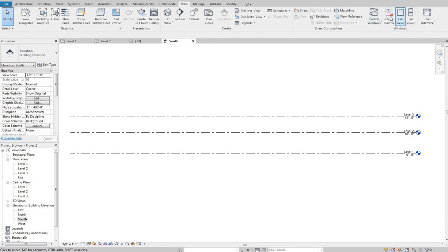So I'm on the south. If I hit close all inactive, it gets rid of all of the open tabs here other than south. So if your file's ever running a little slow, that's not a bad way to help speed things up a little bit. Close the inactive views, and it'll kind of reset for you.